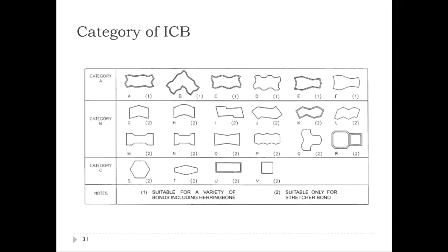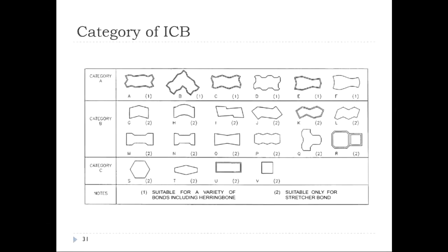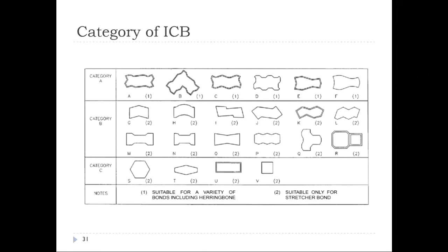And even if you look at residential areas, in order to make these interlocking concrete blocks more fancy, different varieties of shapes are also available in the market. But some of these shapes would actually result in bending stresses in these blocks, and as a result you will find these blocks undergoing cracking. So you should be careful while you select the paving block shape.